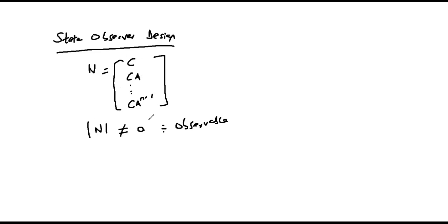The system will be defined in state variable method, or will be modeled using the state space model. And then we proceed to design a state observer based on the required locations of the poles for our given system. Suppose our system is defined by the state equation, x dot of t equals Ax of t plus Bu of t, and the output equation is y of t equals Cx of t.